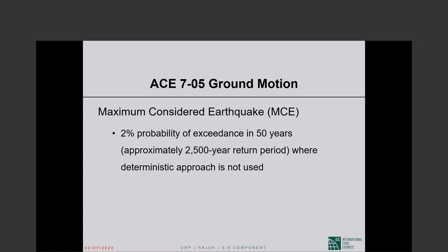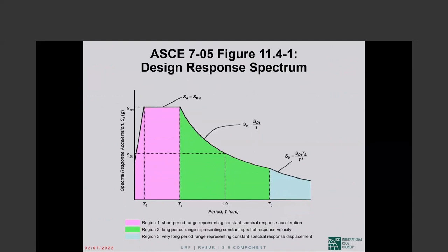So this is the maximum considered earthquake for our purposes in Bangladesh. This is the 2,500-year return period earthquake, 2,475 years to be more exact. So we come back to the design spectrum or the design response spectrum of ASCE 7.